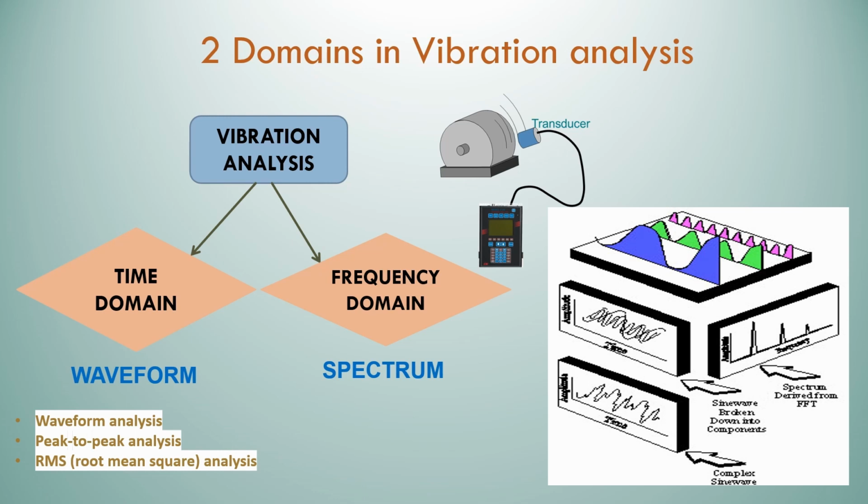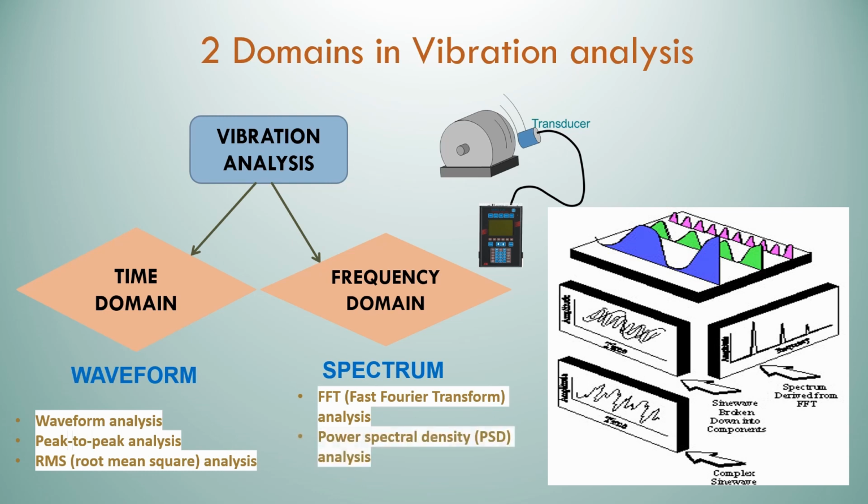Frequency domain analysis focuses on decomposing the vibration signal into its constituent frequencies and their respective magnitudes. Common frequency domain techniques include FFT, fast Fourier transform analysis, power spectral density (PSD) analysis, and frequency spectrum analysis.